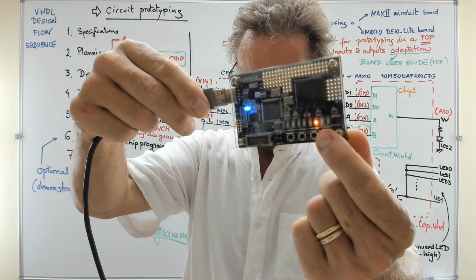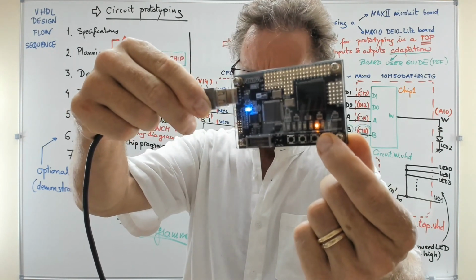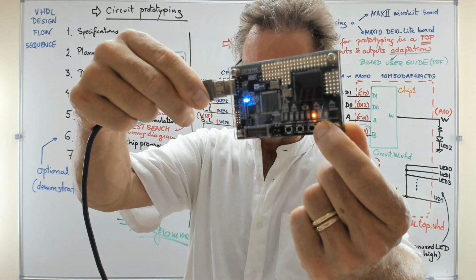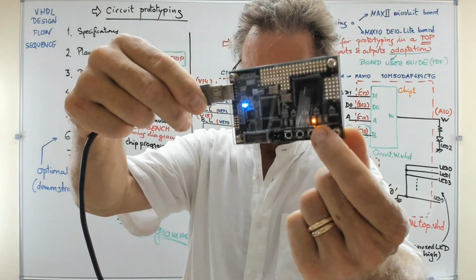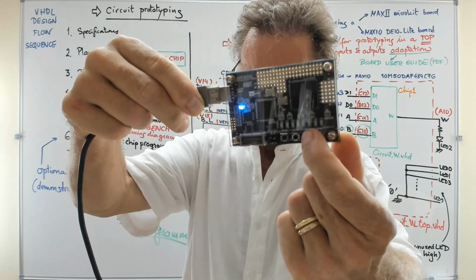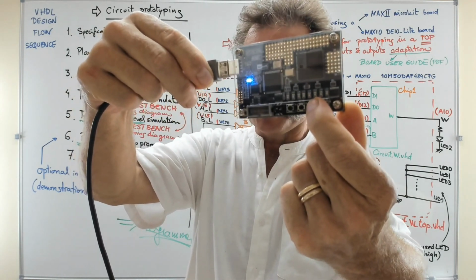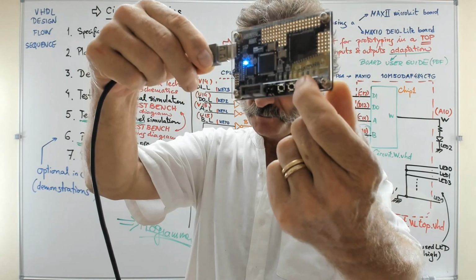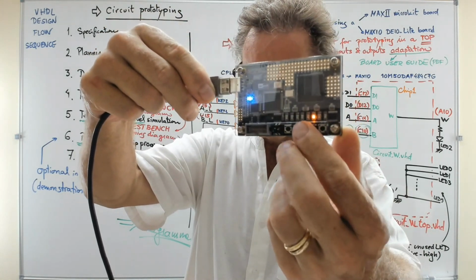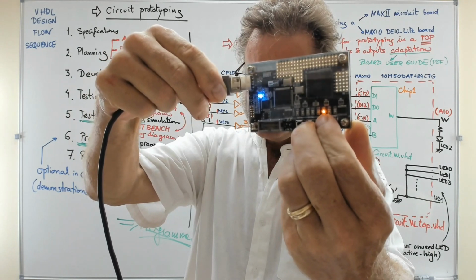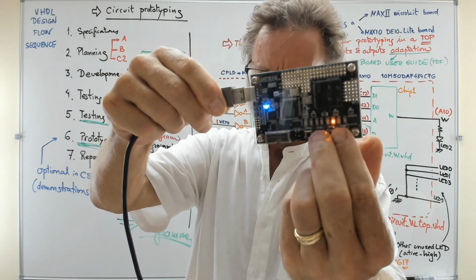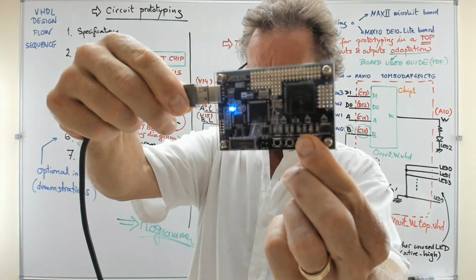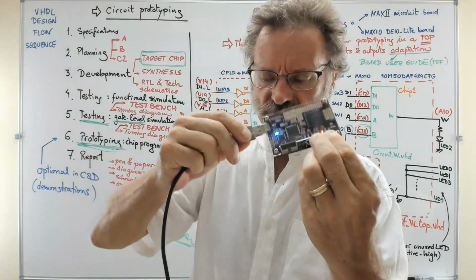And then, for example, if you click the 1, you are inputting 0, 0, 0, 1, and this is another min-term, so the LED is still lighting. But when you click 0, 0, 1, 0, like now, you have a max term, because 0, 0, 1, 0 is the max term 2 in this circuit, so you have a 0 and the LED stops lighting. And then when you click the 2 and the 3, in the same way you have another max term. And the same when you are clicking the 3 of them.